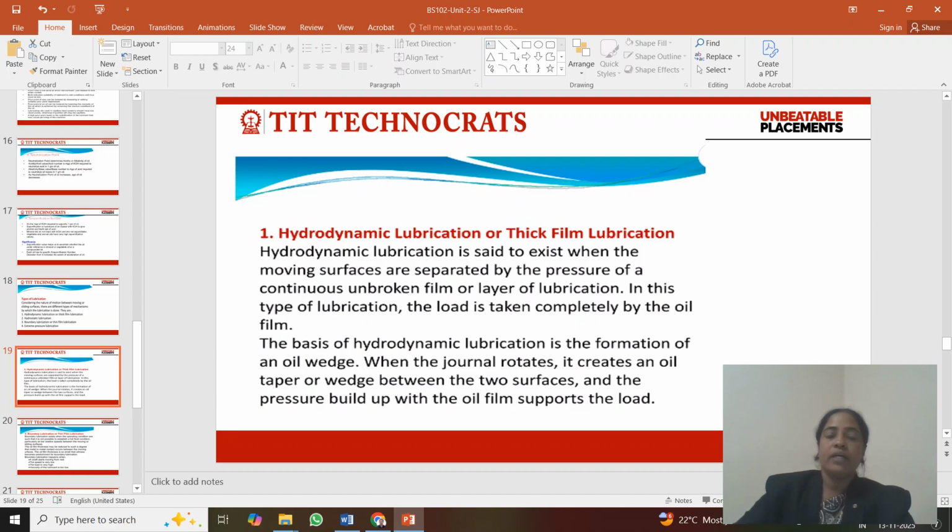If we talk about the hydrodynamic lubrication or thick film mechanism, in this mechanism the machinery parts absorb a bulk quantity of oil between them. Basically, during thick film lubrication, between the machinery parts, at least 1000 angstrom of lubricating oily layer or bulk layer is required to control the friction over the surface.